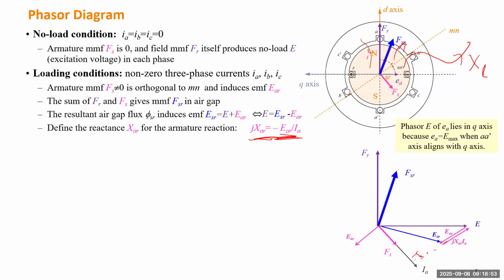If we just use a battery as an analogy, this is like the terminal voltage if it's an ideal generator without leakage flux, without resistance. But if it has some resistance and leakage flux, whatever voltage we get outside of the generator is not even this one, it can be even shorter. So we have to consider the voltage drop on the resistance and also the leakage reactance.